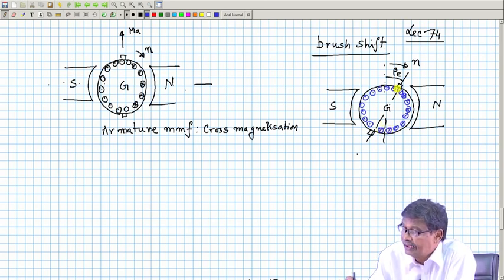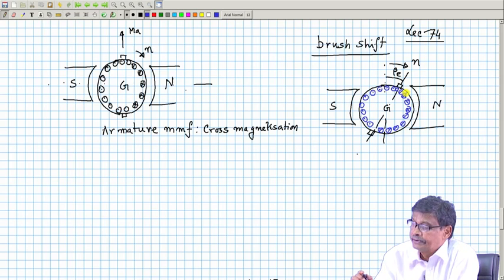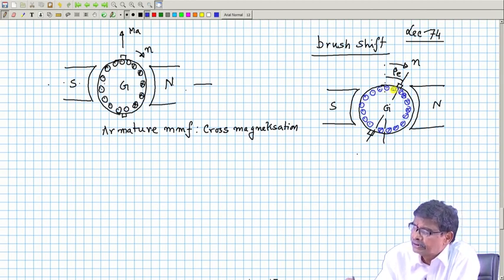Up to this point cross, and here is the conductor which passes this magnetic neutral axis. It will be the quadrature axis; this is the quadrature axis, it is now shifted here. So, you give some brush shift. Why have I given the brush shift? Because the conductor's induced voltage under the south pole is of dot polarity, but this conductor is going into commutation, its current will switch over from plus I to minus I as it crosses this brush position. Therefore, this conductor started inducing voltage dictated by this north pole a little earlier when it crosses the brushes.